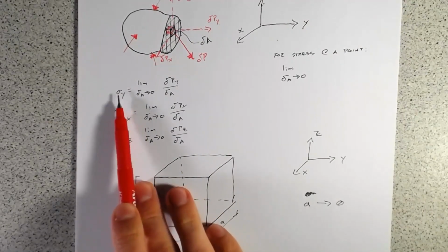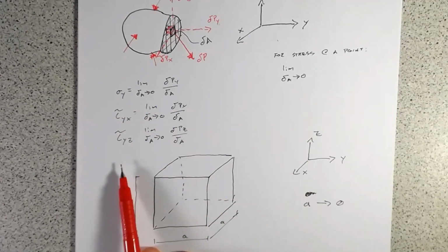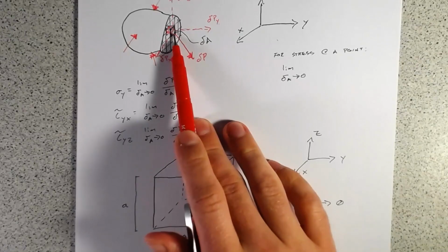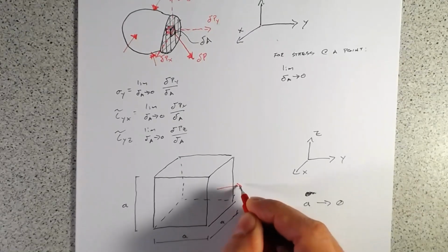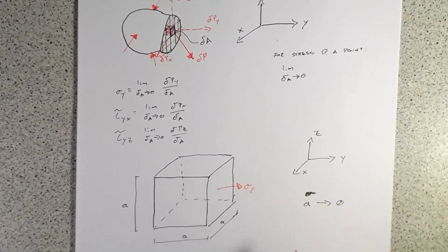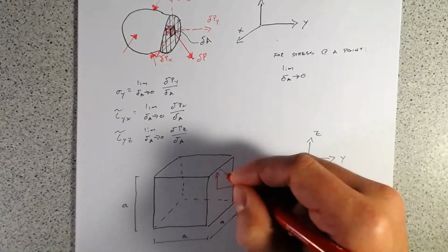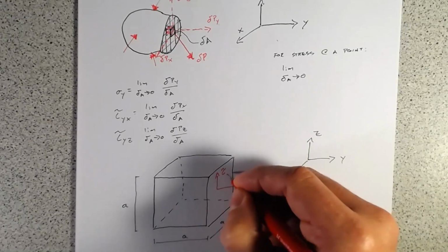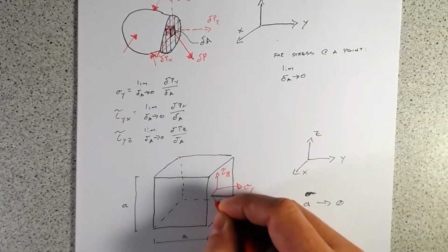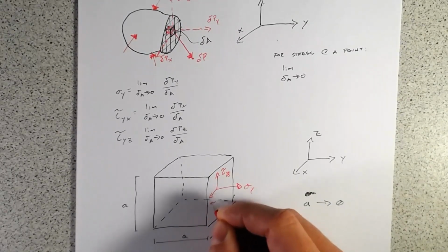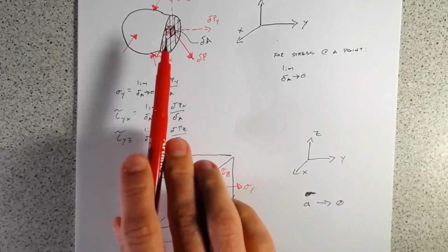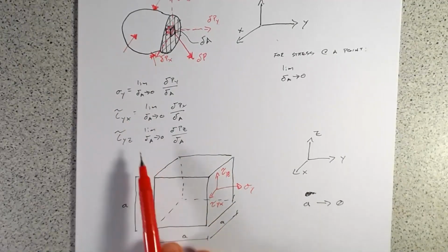Essentially, we've worked out what each of the stresses are on each of the faces. So on this first face, which was right here, we've already drawn that. So we have a stress sigma y. And then we also have a shear stress tau yz, and a shear stress going in the opposite direction, so going orthogonal, sorry, tau yx. So we've just drawn this and basically this definition right here.